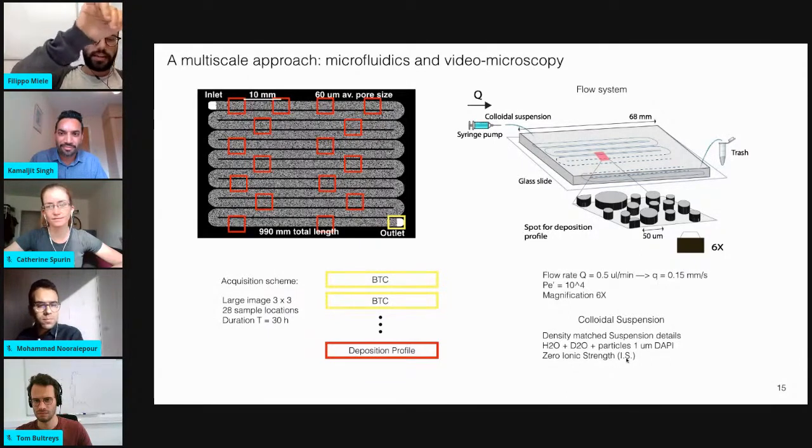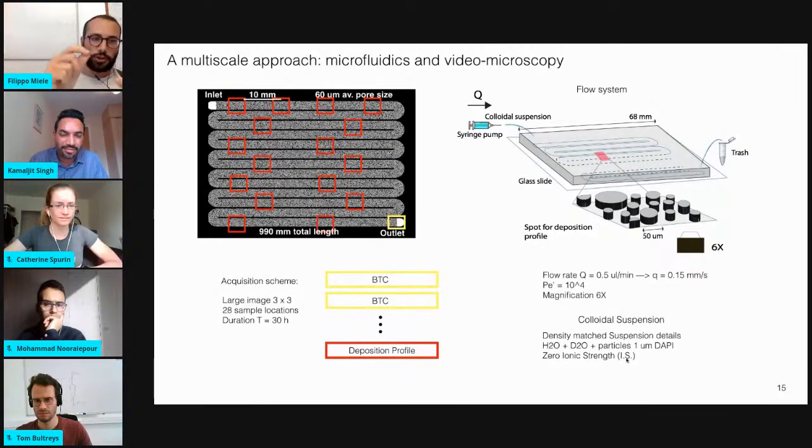Basically this is a parameter of the particle tracking that tells you the maximum distance over which you may find two candidates, which is given by the maximum velocity and the frame rate at which you are collecting particles.